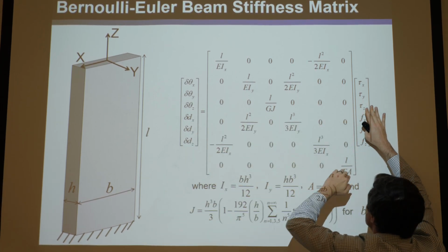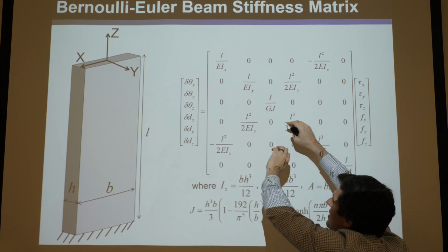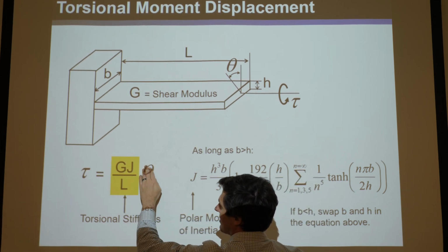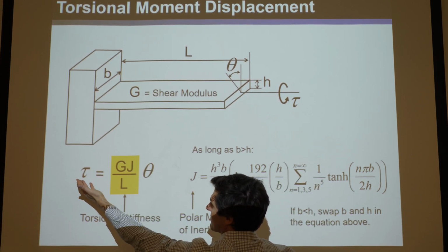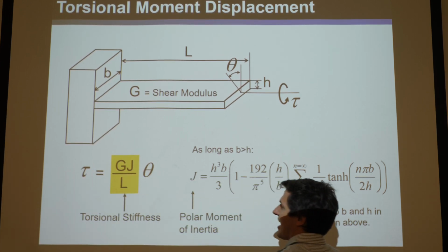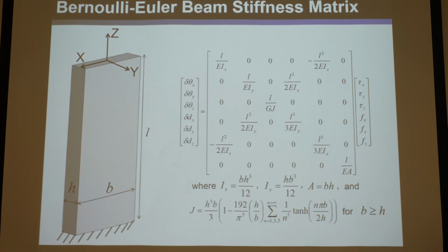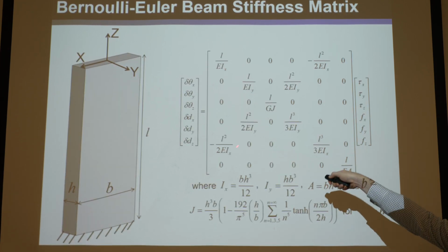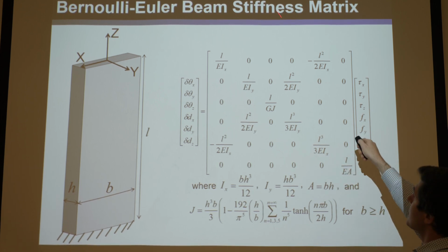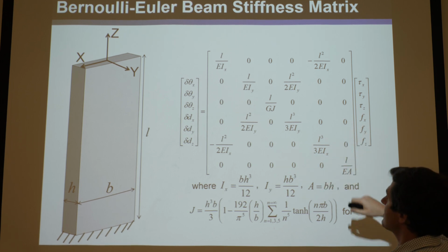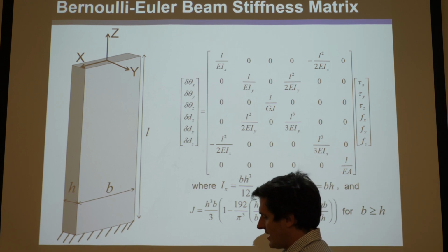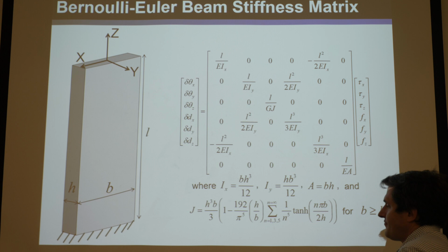Since we're timesing these loads by something to get the outputs, that's why we switched all these directions. In this case, we plug in the load input and get the output displacement, so we had to flip these to multiply the load to get the output displacement. You can see all these equations are very familiar. They're just flipped, numerator and denominator flipped upside down. You might also notice some of them have negative or positive signs, and let me explain how that's the case.